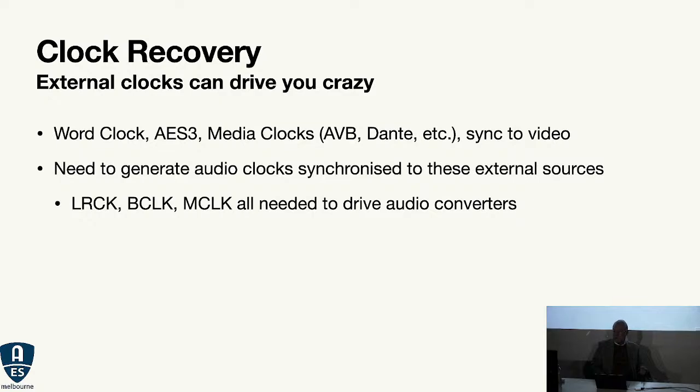Just like standards and jitters, everybody's got a name for their own version. You have a bit clock, which clocks the digital bits in your stream. And you have what is commonly called M clock, which is the one that really needs to be clean, because that's what drives the sampling part of an ADC or a DAC.